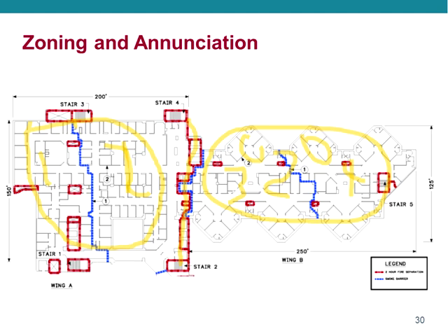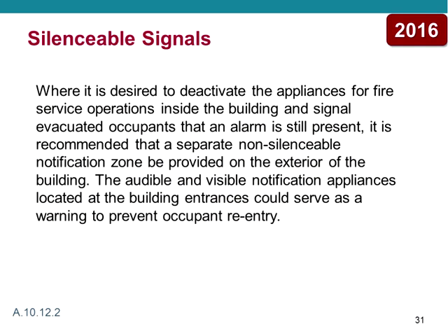In this intensive care unit, in this example, these are ICU, the patients aren't capable of evacuating. So what do we do? Well, we try to defend in place or relocate, but only if necessary. So that's why we have ECS that operate for up to 2 hours during an emergency, so that we can direct aid and relocate and get people out of harm's way in an orderly fashion. Whereas in a typical building like a Home Depot or a Lowe's, you're going to evacuate the entire building at one time, and we give you 5 minutes to do that. And that's a totally different case.